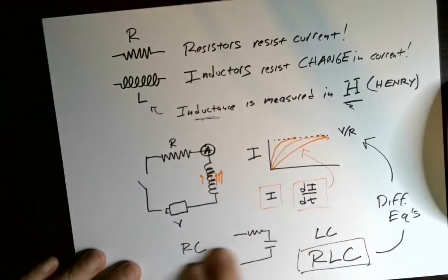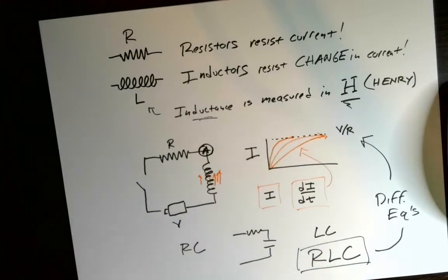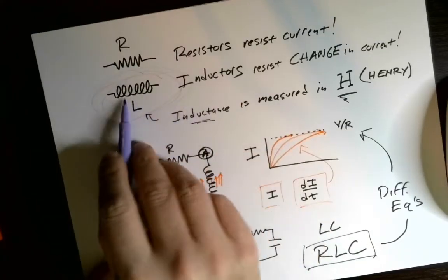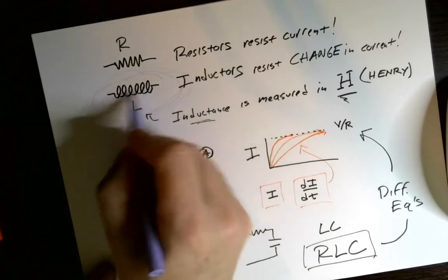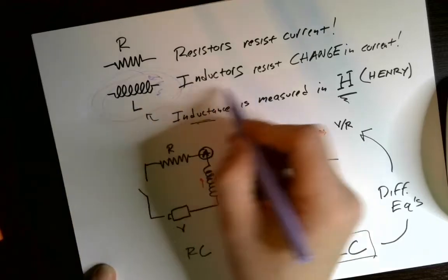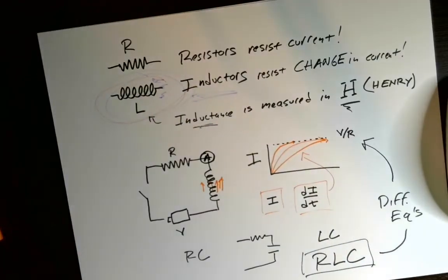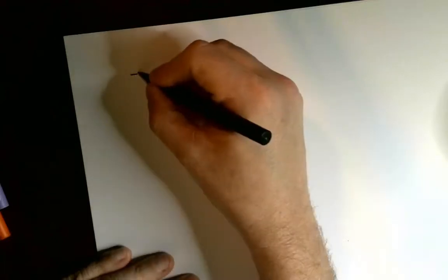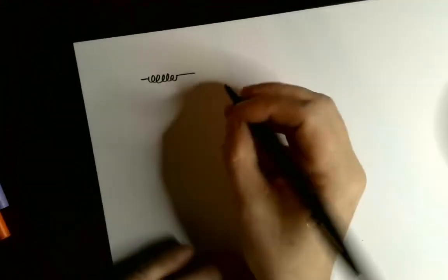Last time we were talking about the idea of an inductor, which is a circuit element that just looks like a coil of wire, and because any changing current in that coil will change the flux through that loop and cause an EMF due to Faraday's law in the opposite direction, inductors resist any change in the current. Let's look at this a little more specifically. For example, we didn't write an equation for what inductors do or define the inductance very precisely. So let's do that right now.